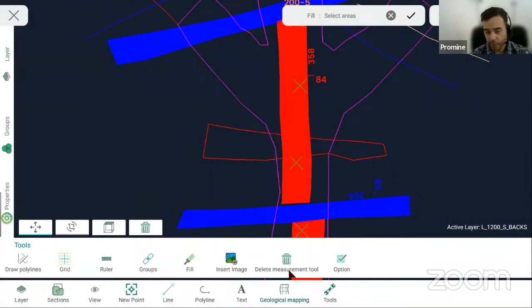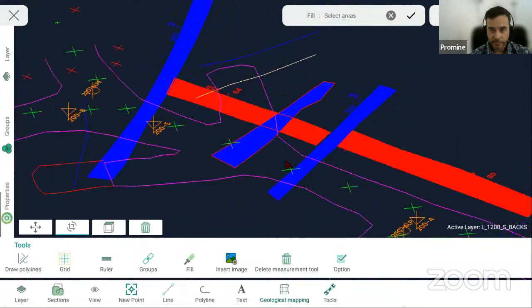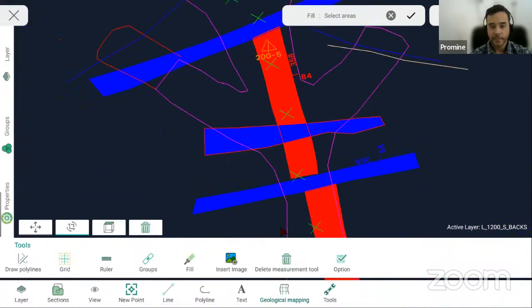It's giving me a report of the actual elevation of that line. And now I only have to click inside of the part that I want colored. So I'm going to tap inside of that red line. And there I have my hatch created at the 1200 elevation.